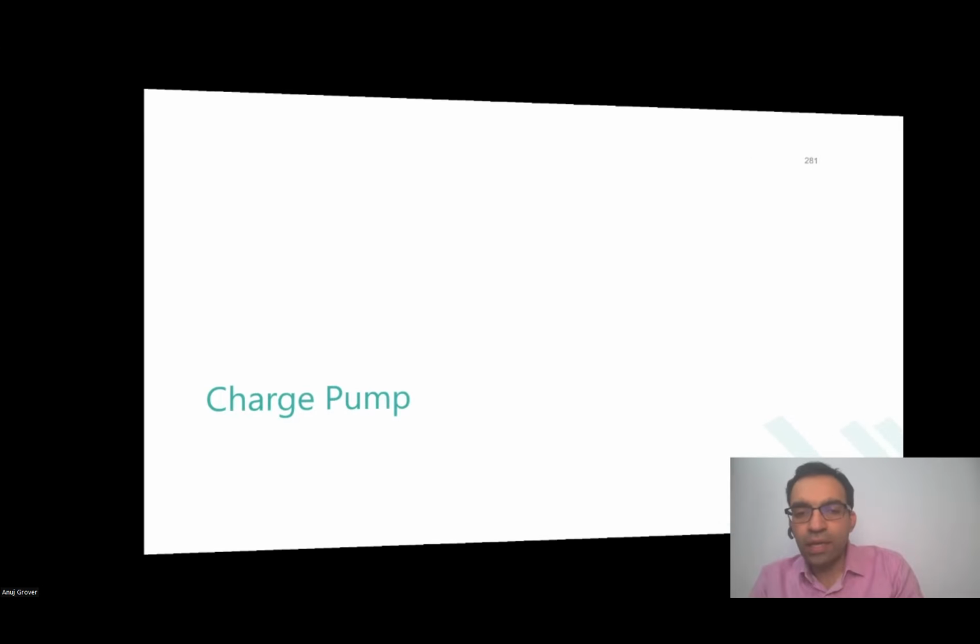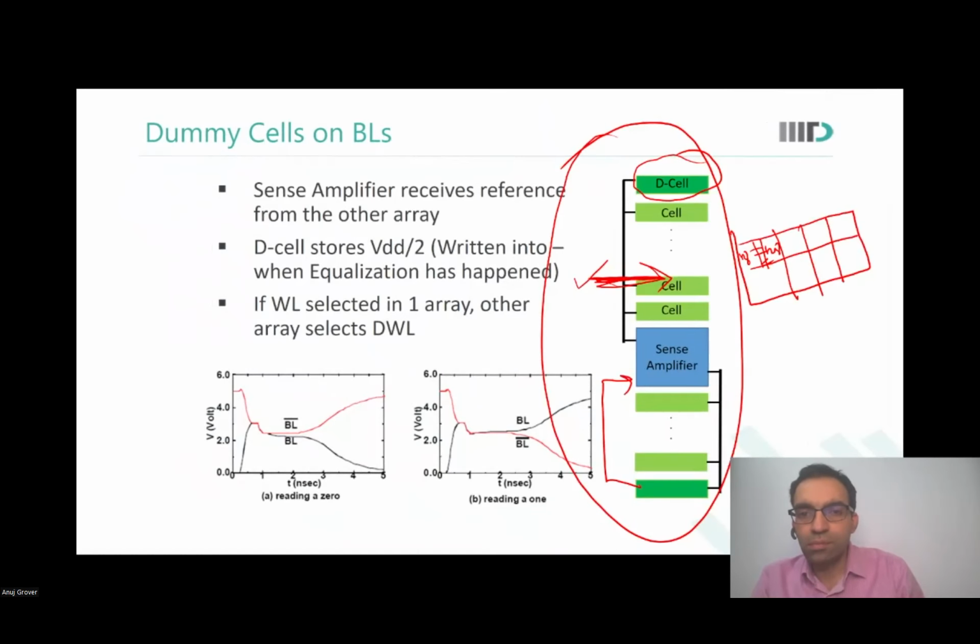Any further questions here? About the sense amplifier operation, the bit line connected to the precharge point, the internal node we precharge, like earlier we had a device to distinguish between them. Now the internal node precharge and bit line precharge became the same, like they are shorted, right? Yeah. In DRAM, yes, that is what happens. As you read, the refresh also happens simultaneously. I'm not talking about refresh, I'm talking about the precharge.